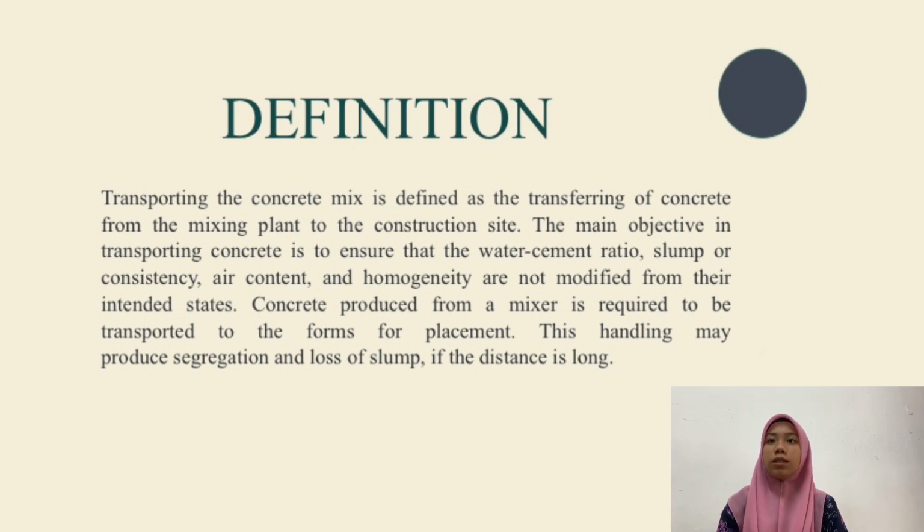The main objective in transporting concrete is to ensure the water-cement ratio, slump or consistency, air content and homogeneity are not modified from their initial states.